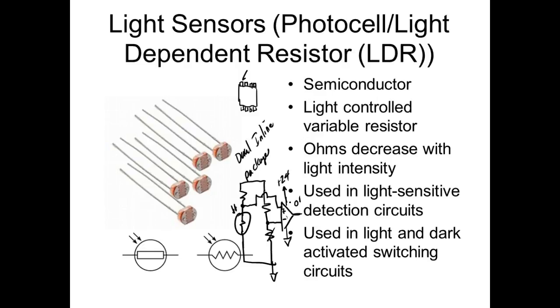So what they'll do, even though the output of this is an analog, this is going to take it and convert it into a single bit digital output. So a lot of the sensors that we run into, guys, the actual sensing element is analog. But when we see it, we get what? We get digital.